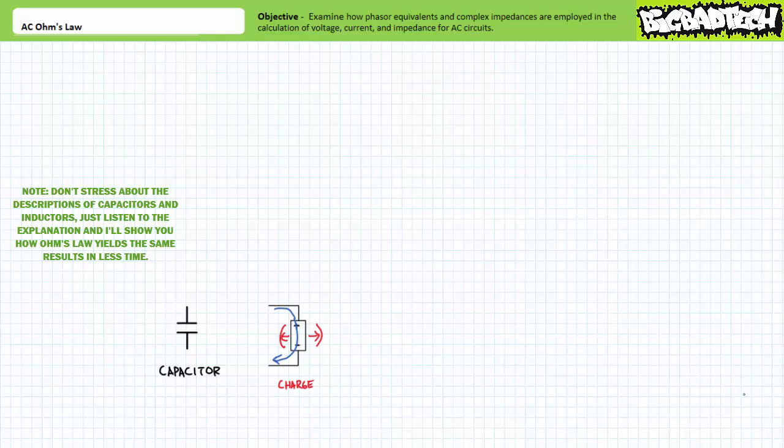Current flows into the capacitor, top to bottom, and an increasing voltage differential develops across the capacitor, positive to negative, top to bottom. In this sense, the capacitor is acting just like a passive element, absorbing energy. When a given voltage potential has been reached, the capacitor then begins the discharge process. During discharge, current would flow out of the capacitor, top positive terminal. However, a decreasing voltage differential is still experienced across the capacitor, positive to negative, top to bottom. In this sense, the capacitor is acting just like an active element, supplying energy.